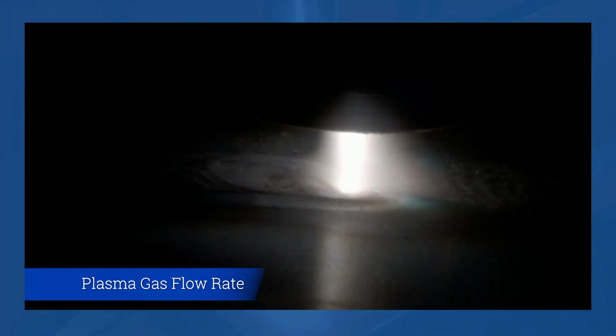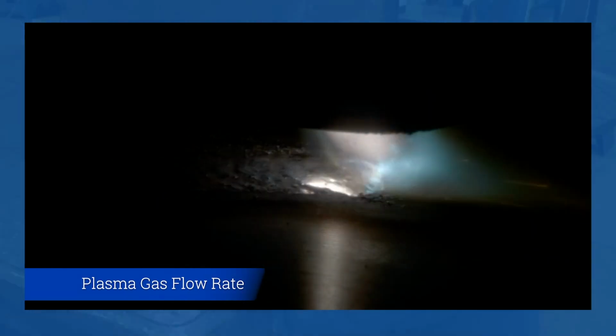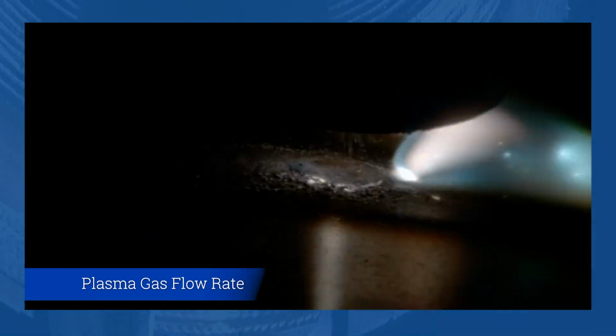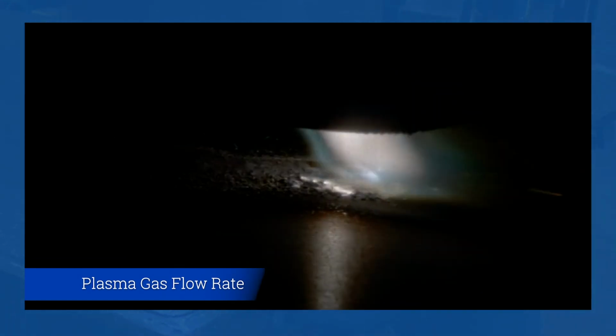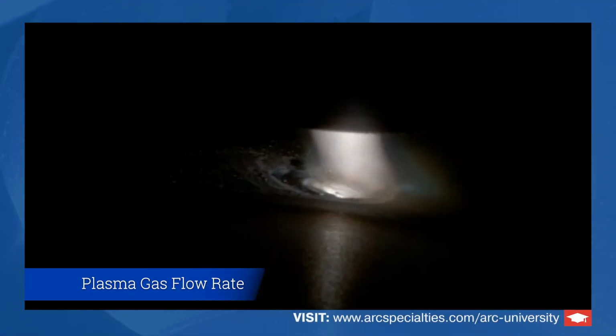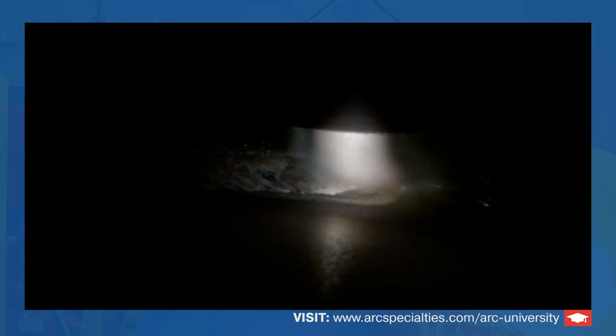And now we're going to turn it down. That was up to 8 cubic feet per hour. We're going to turn it down. This is kind of dangerous because if you don't have sufficient flow rate, you can actually damage your torch with double arcing. So obviously too low, but that's 1 cubic foot per hour, and 2 is optimum. We're back to the optimal 2 cubic feet per hour rate, and we're making a good weld.